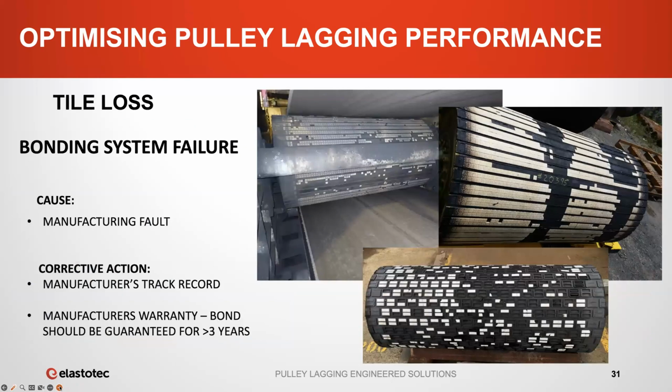Let's first of all talk about bonding system failure. Basically, it's a manufacturing fault, and there's a whole range of different causes, but it is predominantly a manufacturing fault. It's the most common form of ceramic tile loss or ceramic lagging failure. Things that you can do to overcome this is basically evaluate the lagging manufacturer's track record with regard to tile loss problems, and then find out what sort of warranty is provided against tile loss.